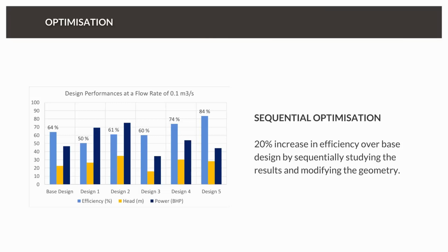What we put inside the system can be calculated mainly due to the mass flow, and the power can be calculated based on the pressure forces or the fluid forces acting on the impeller. So this is basically a different direction. Usually you first calculate your power and then your efficiency, but in the end it will result in the same.